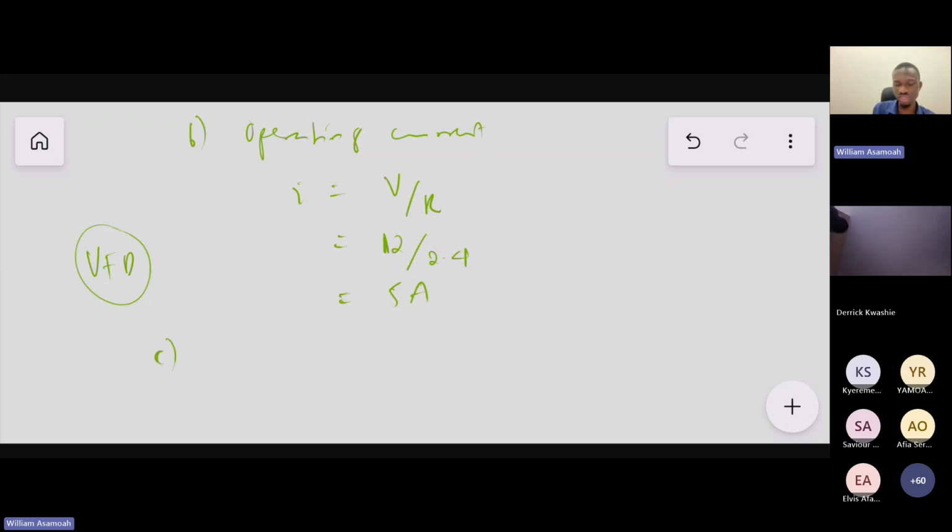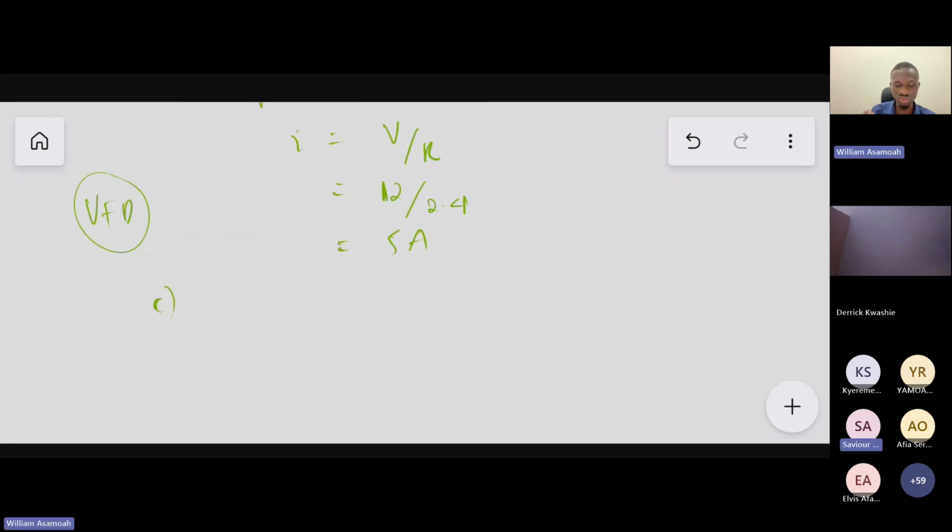At that time the resistance is low, it draws low current, then they gradually increase the voltage over about 5 seconds so that it doesn't draw instantaneously. Because in an industrial setting, if you are dealing with industrial motors and it's drawing suddenly, you can burn the whole system down. So it's very, very critical. We take a look at that when we are designing our systems.